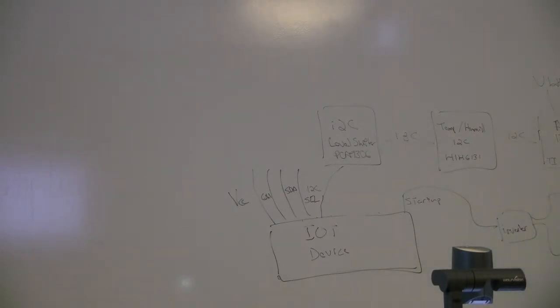I'm asking because I'm working on a project. I'm using an MCP23008 port expander. Okay. And I'm going to power it. I only have 2 connections, excluding ground, to my Pi, which would be SDA and SCL. Right. So I'm receiving no power, nothing's going from the chip back to the Pi.